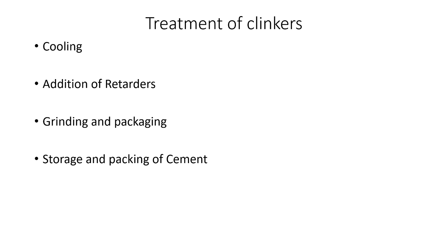Storing of cement for some time before packaging is beneficial. Okay. Prolonged storage of cement in packages, especially in moist air, decreases the strength of cement due to partial hydration and formation of coarse particles. So that is very important. So this is the storage and packing of the cement.